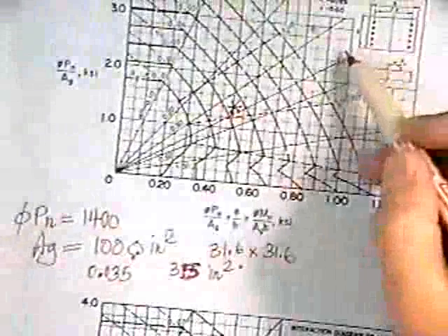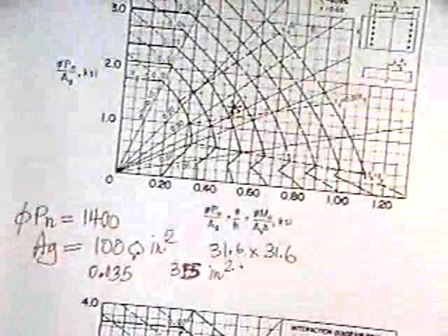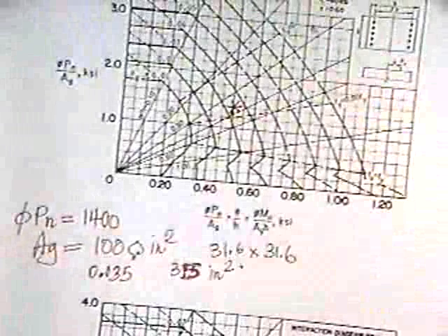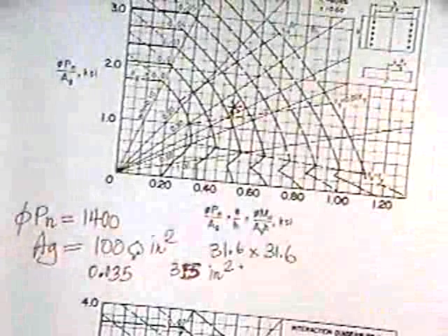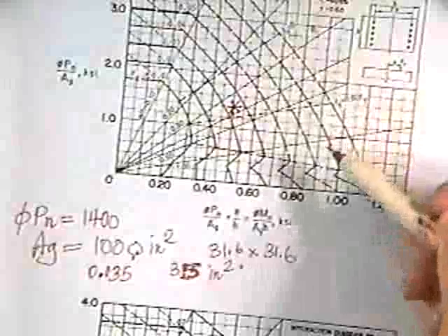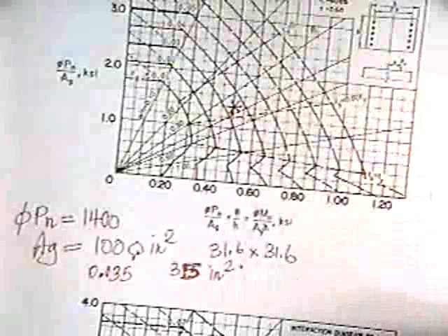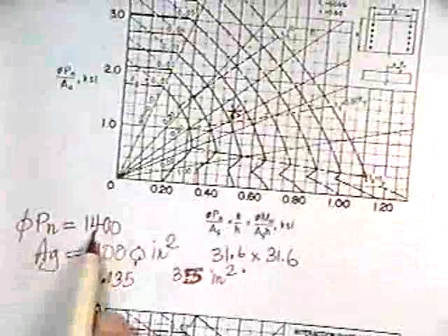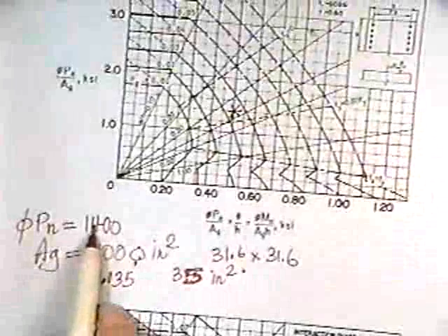Well, for this diagram, you'd have to put half the bars in. Take 35 square inches and divide by 2, put on both sides. And then go find some reasonable number of bars that gives you half a 35. Yeah, I selected a P that was too high.